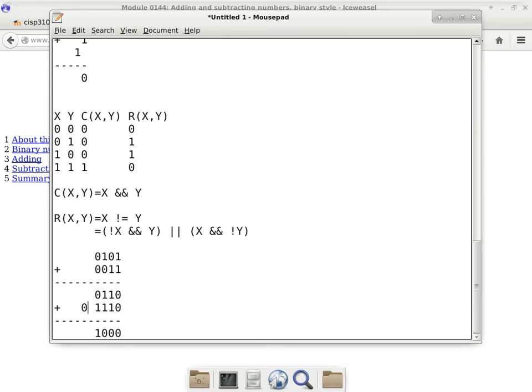Now this carry doesn't seem to be useful at all, because after all, we are only dealing with 4 bits. But this dangling carry is actually important when we design the processor. We'll deal with that later. But we do want to calculate what is the actual carry from the most significant column. Are we doing okay so far with this one?